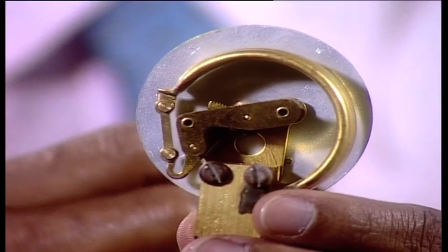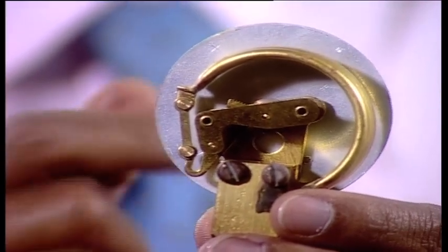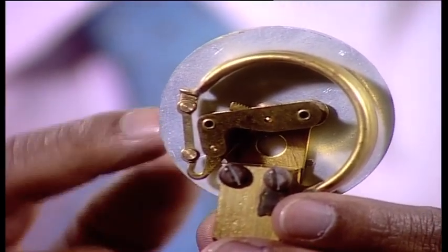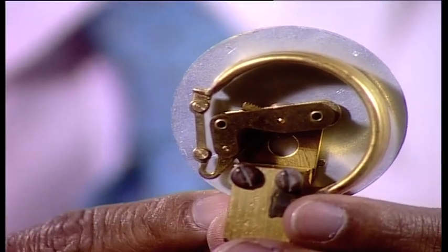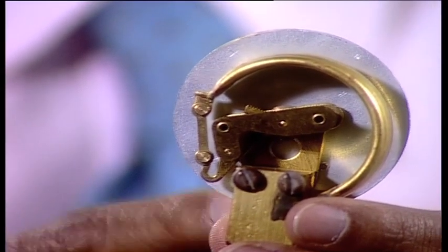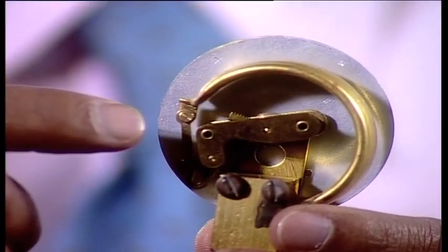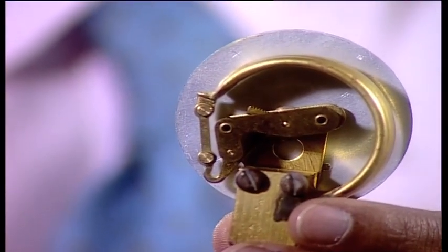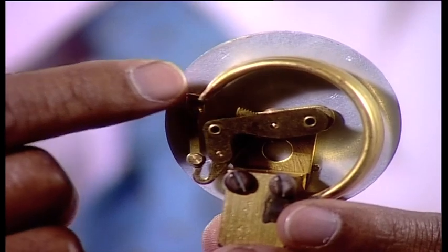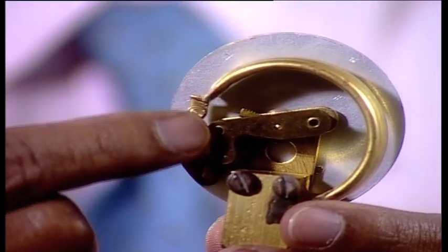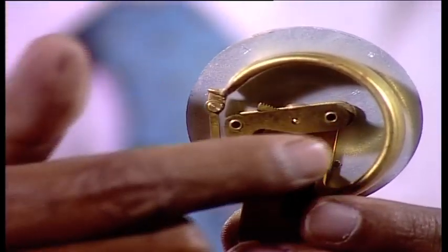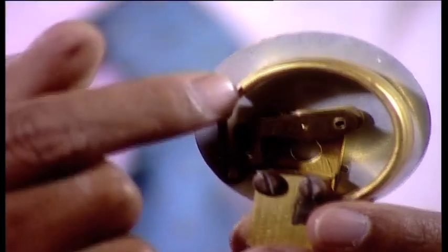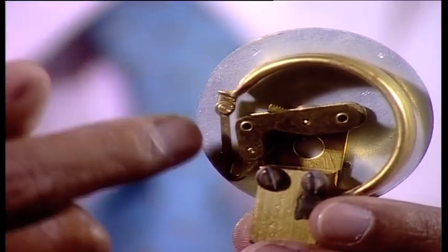Now, the advantage of that type of thing is that I am getting more deflection, because usually this is for quite high pressure. But if I have a longer length of the C tube, because if I make only a single C, I will not get much deflection. So, instead of that single C, if I make a spiral, that does not end here, it comes down these, we have several turns, then it ends, and that closed end is again connected to the lever.